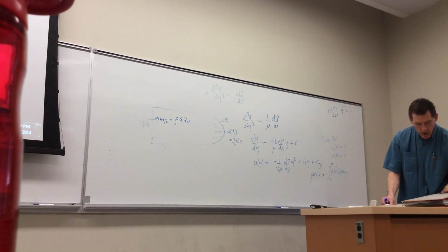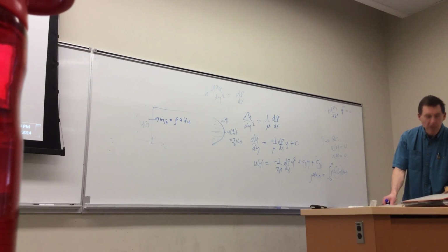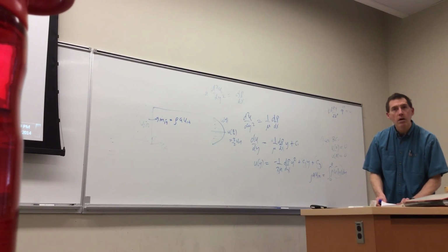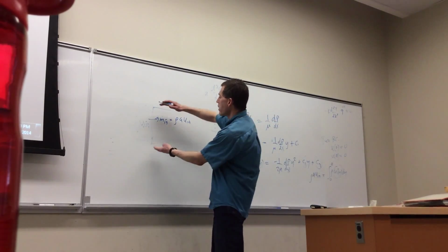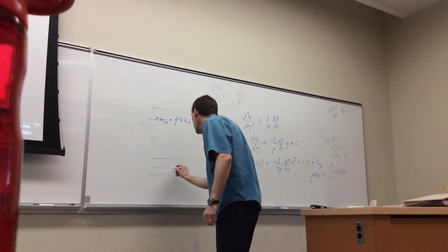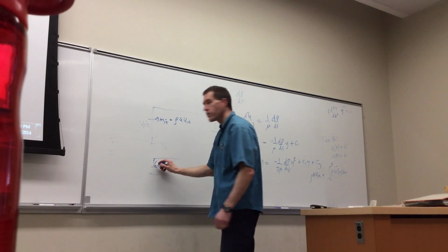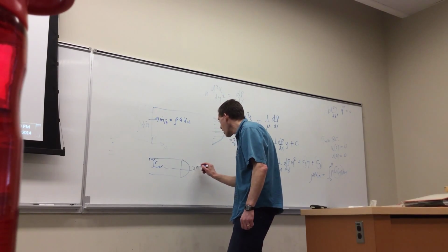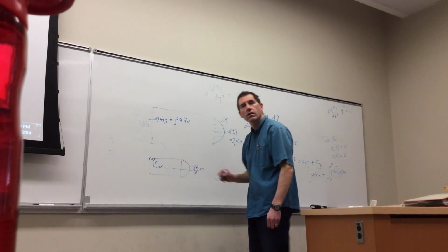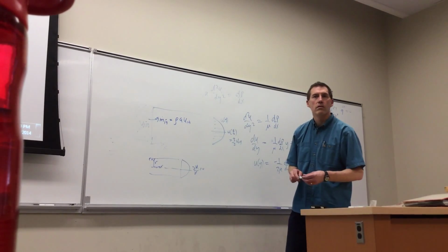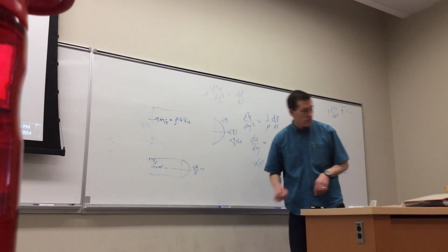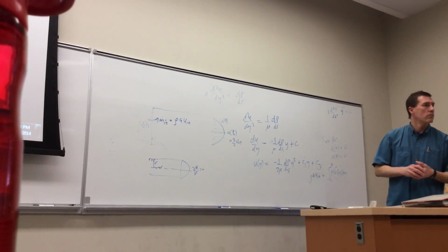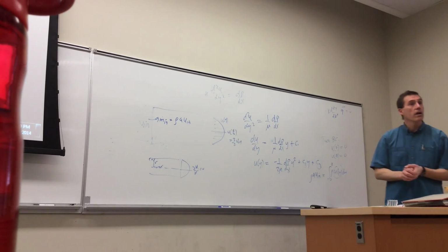And they come up with a profile on the top of page 522, which is the U over U mean, which is UN. But the boundary conditions that they use are U at R is equal to 0 and dU/dR equals 0 at the center. Yeah, because in the tube, okay, this is parallel plates. If you're doing the tube, then your coordinate system goes from the center to the wall. So if this is R0, here it's symmetry, right? dU/dR equals 0 right there. So it's symmetry here and 0 at the wall. Okay, is that sufficient, or okay?